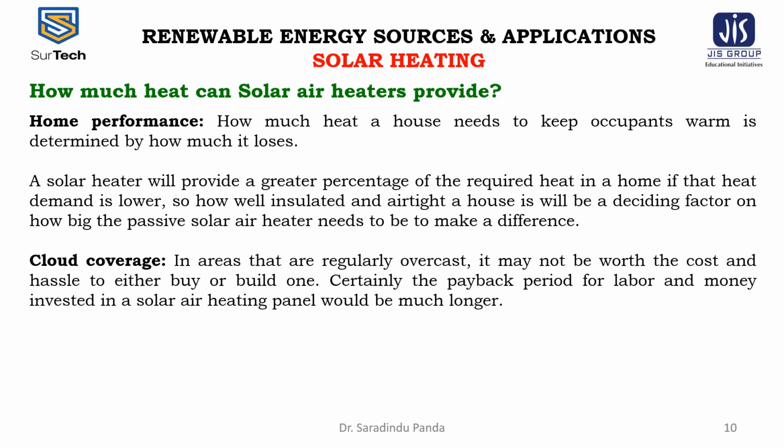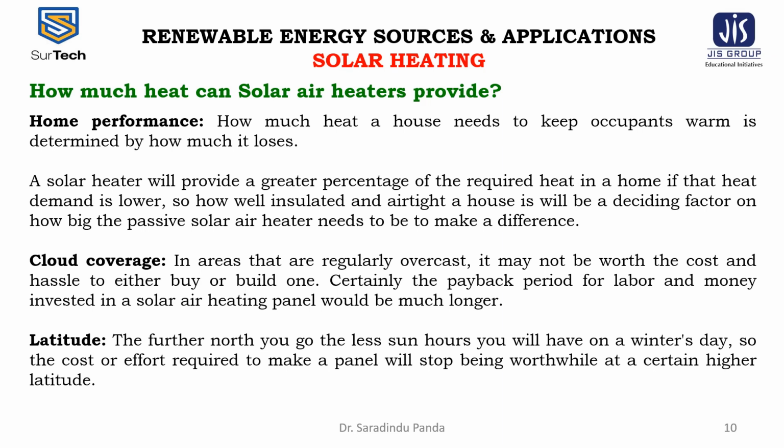Next one is the cloud coverage. In areas that are regularly overcast, it may not be worth the cost and hassle to either buy or build one. Certainly, the payback period for labor and money invested in a solar air heating panel would be much longer. Latitude. The further north you go, the fewer sun hours you will have on a winter's day, so the cost or effort required to make a panel will stop being worthwhile at a certain higher latitude.